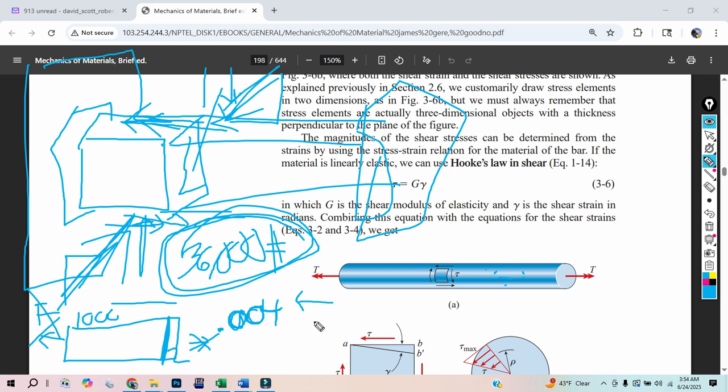So that's also what this 0.004 angle means. And what we do is we draw a little square on this, and I say, hey, if you can register that angle of 0.004, which is very, very small, it'd be hard to calculate, then you better stop and then let go, and then you'll just have the original bolt. But if you go farther, then this bolt is going to start permanently bending and becoming a sheared bolt.